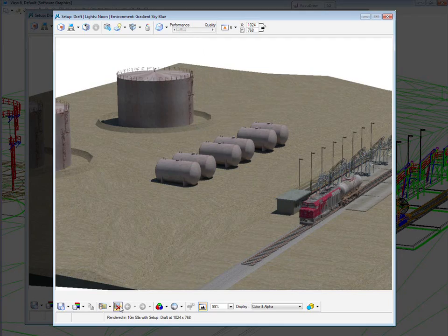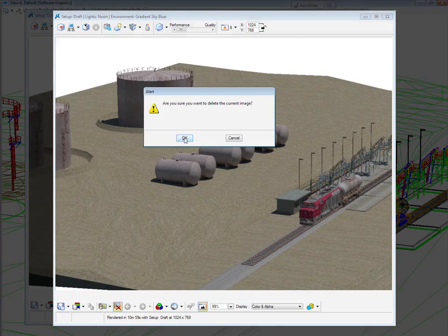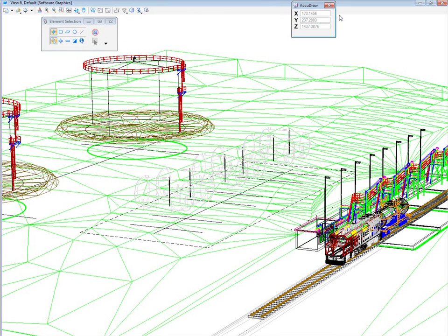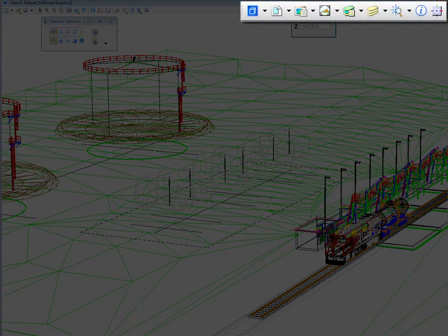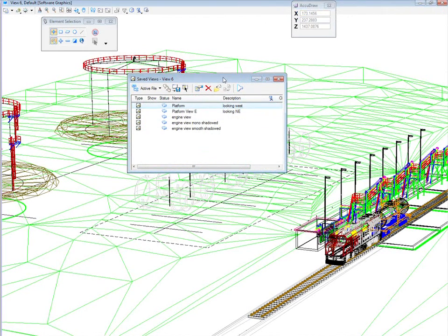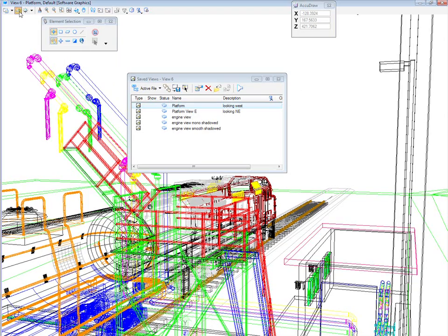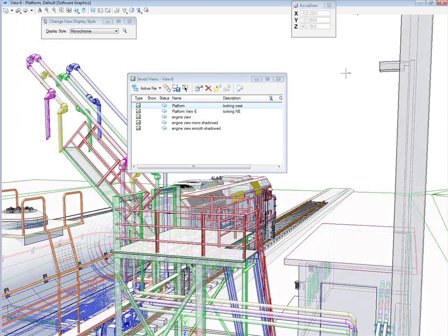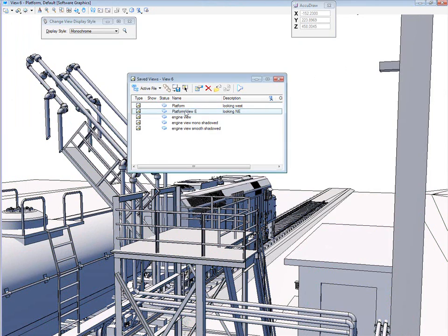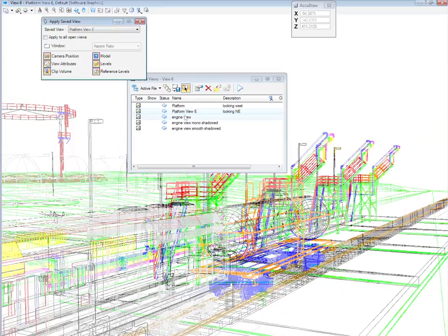There's another way of doing it too. What we're going to do here is actually delete this current image and minimize Luxology, because Luxology is great. It runs in the background. As a multi-threaded part of MicroStation V8i, you just minimize it. It can do its own business. It'll be okay, not a problem. Because what we can do, we can come up to our primary toolbar. We can go to our saved views. And inside our saved views dialog box, we have 6. So if you just want to click on some of these, double click and then click once in your view, you can quickly see, and you perhaps put a display mode onto it, which view mode you would actually like to see and process next.